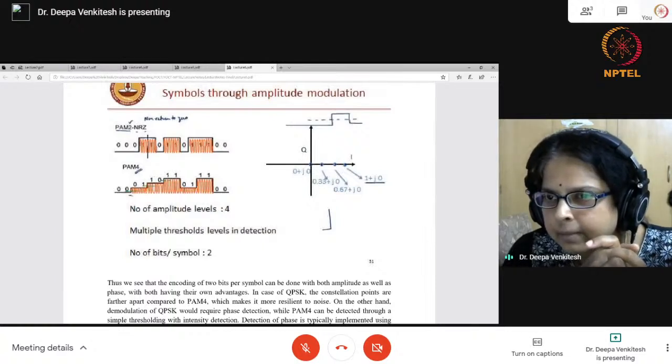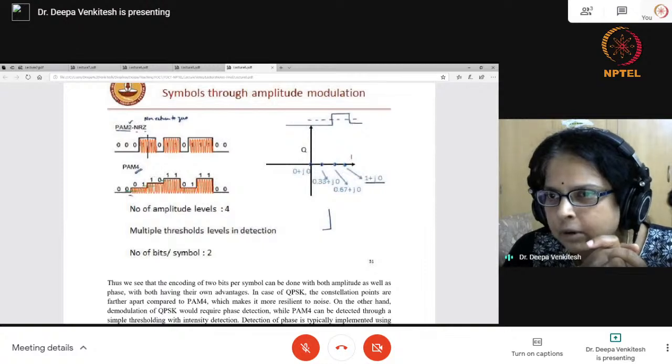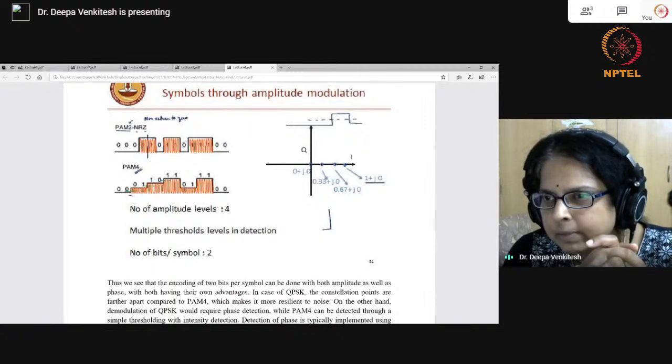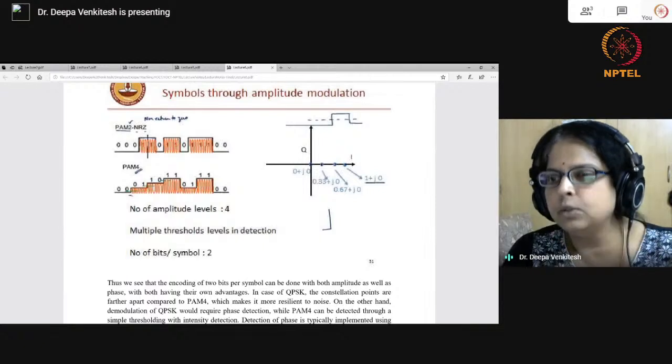There's a question from Michael Jordan. If I want to transmit data at 100 Gbps, I can go with either 64 QAM or a WDM system with 4 channels of 25 Gbps. I would like to know which one would be better with the 1310 transmitter system, where there is no dispersion.